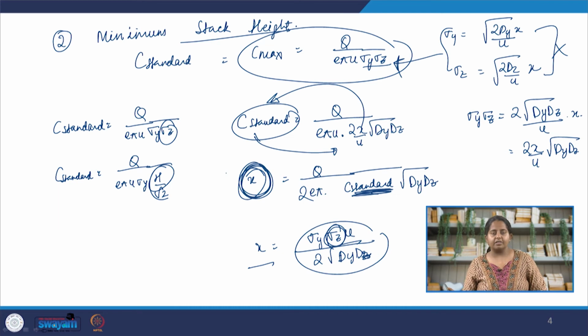Now I want to discuss what I promised you I will discuss, atmospheric stabilities, and give you some visual ideas of how the environmental lapse rate or atmospheric lapse rate and the adiabatic lapse rate together determine the vertical dispersion, the vertical mixing of the plume, and atmospheric stability.